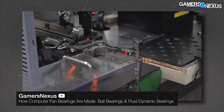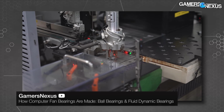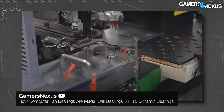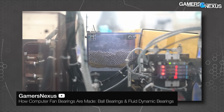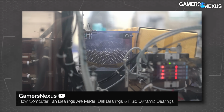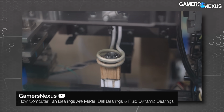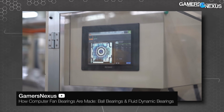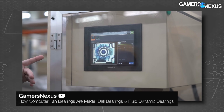And the same would go for temperature requirements. If we have an industrial customer approaching us and saying, okay, we need to run those at 90 degrees constant, we would say, yeah, this is a case where we need to go for ball bearings, because our SSO2 is specified for 70 degrees maximum. I think that's not an issue for any typical PC use case, but for industrial customers it may matter. And coming back to the original hierarchy question, that response could now prompt the follow-up question.